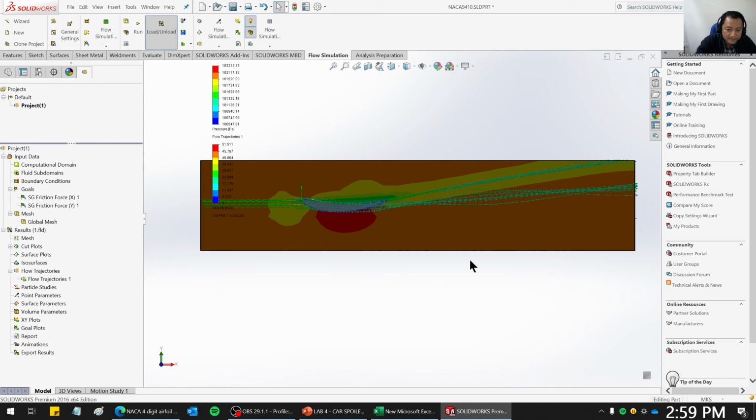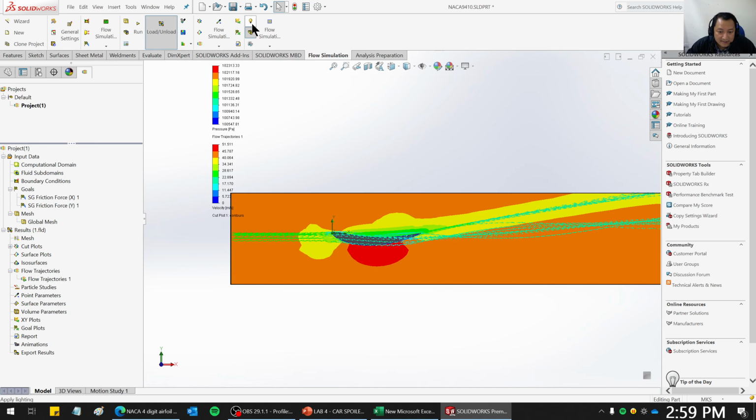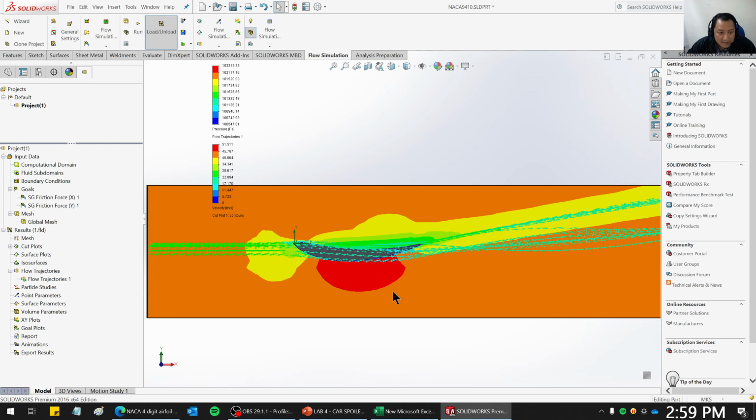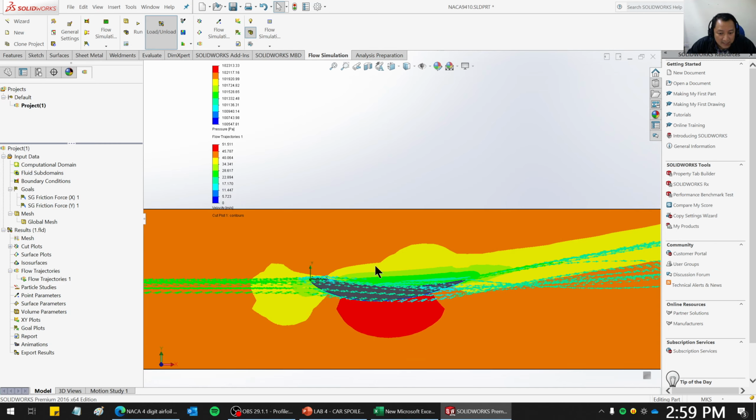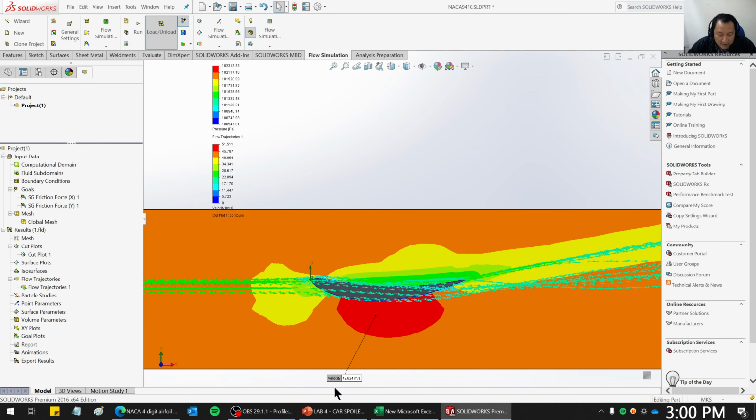Okay. So of course I can turn off this light. Make it brighter a bit. Am I getting higher velocity at the bottom? What is my velocity at the bottom? I can probe, right? Probe using this one. About 50 millimeter per second, 49 something.